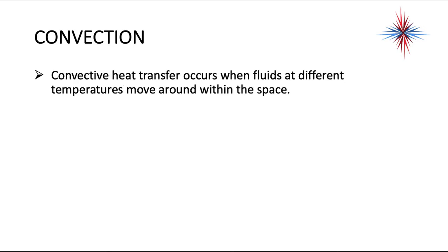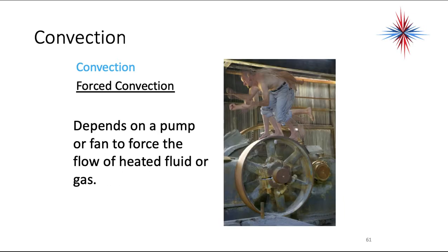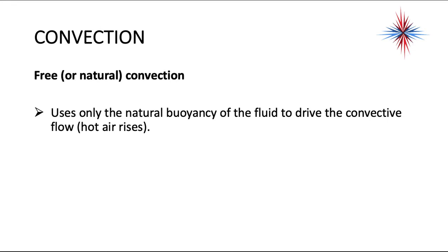Convective heat transfer occurs when fluids at different temperatures move around within the space. Okay. Convection uses the natural buoyancy of the fluid or gas to drive the convective flow of air. Okay, again. Forced convection depends on a pump or fan to force the flow of heated fluid or gas.